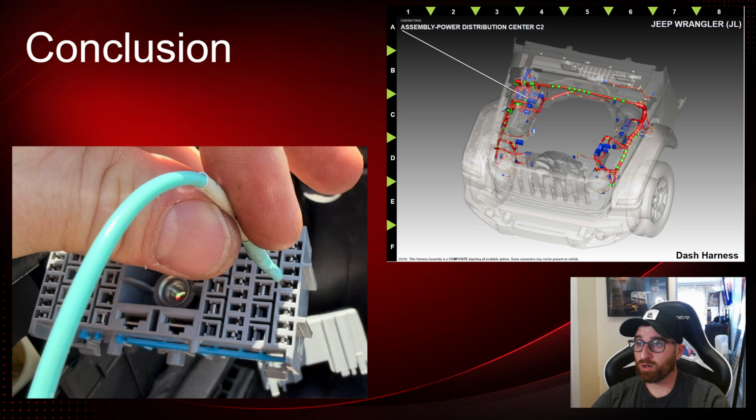I do know on some of these coolant pumps, it is common that if those pumps start leaking through the connector, that coolant can start wicking up through the wires and causing resistance and all types of issues. This one, however, was quite dry, so there were no issues. There was no water or coolant at all.